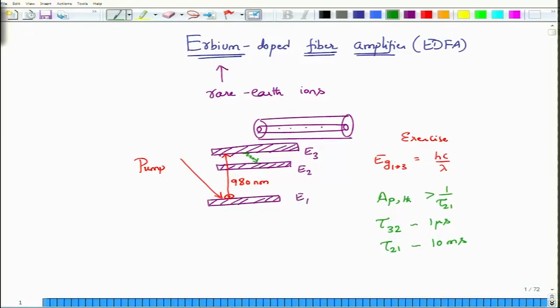In a laser operation, we would actually want a complete inversion, correct. We want delta n to be such that N2 is much larger than N1, and we want almost all of the atoms in the ground level to be pumped up to the intermediate level to create the population inversion. However, because we are not really looking for a laser, but for an amplifier, this condition is not normally satisfied. The degree to which it is pumped is usually given by this ratio, and we denote that ratio as NSP, or the filling factor.